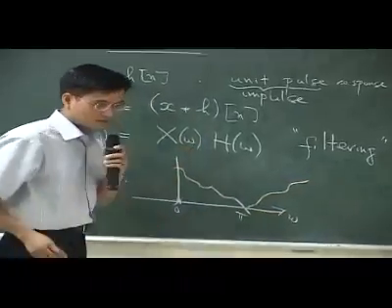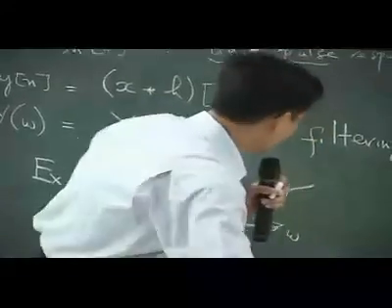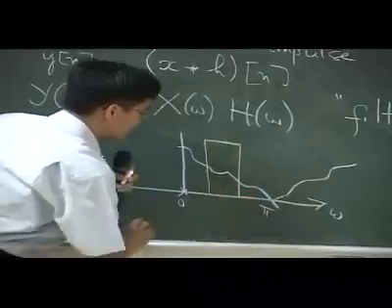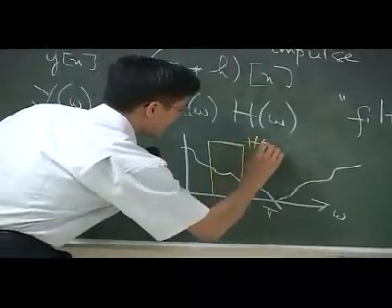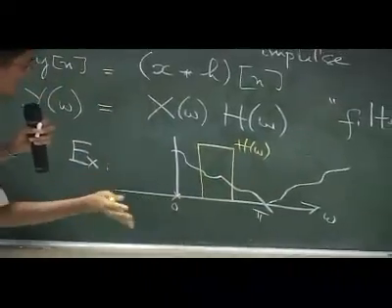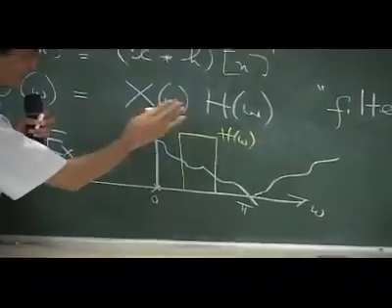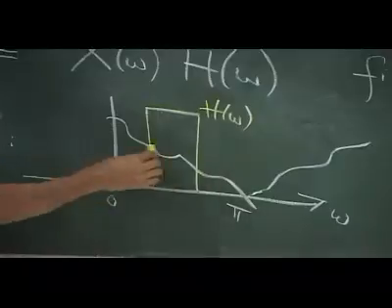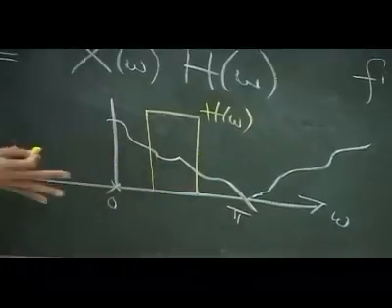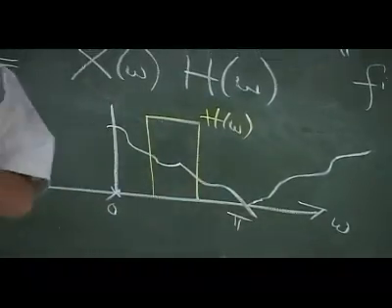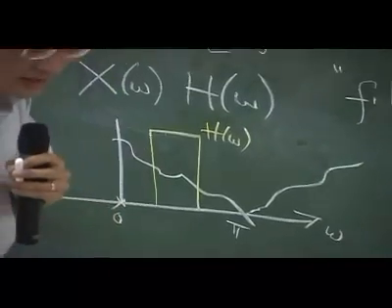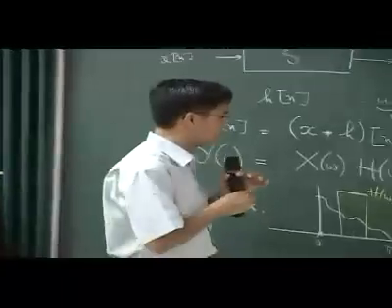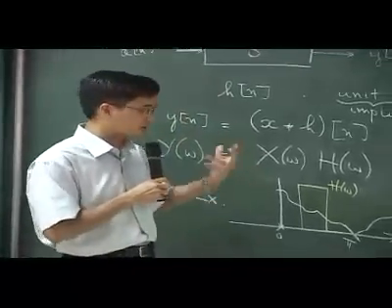So if I have such a signal, and if we think about designing the filter, let's say the filter here is H of omega. So when you multiply X of omega with H of omega, only this part of the spectrum goes through. So that's why I could filter it, right? Just filter out the thing that you would like to go through. So that's why we're going to the topic of filter design or filtering.